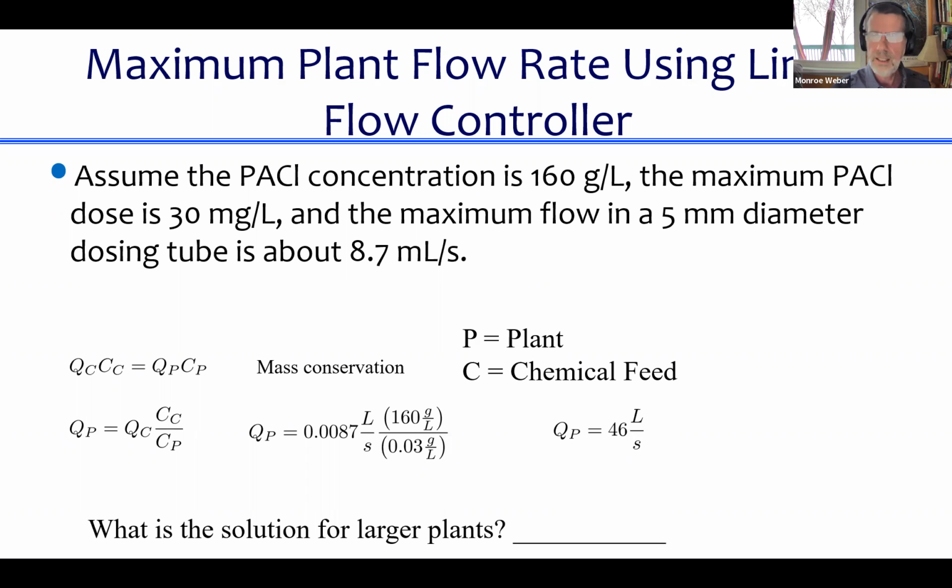And then, oh, this is the QC equation. So this is the equation that a water treatment plant operator has to learn in order to effectively understand what's going on in a water treatment plant. So it's only fair that if you're going to design a water treatment plant, you should also know the QC equation. The QC equation is really mass is conserved, okay? You could think about m dot. The mass rate is equal to the mass rate. That's all this is saying.